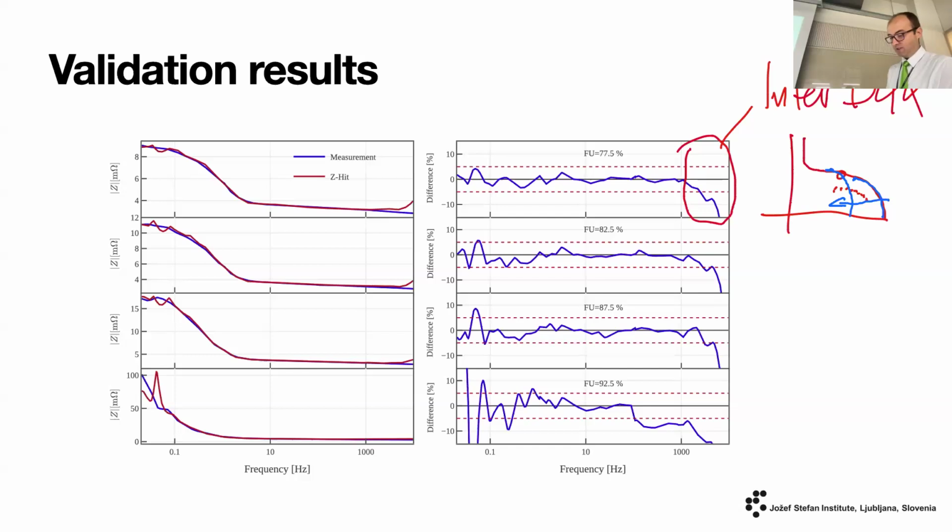And how did we detect it? We detected it because suddenly, even in the low frequency ranges, we start to look for places where our data points start to move out of the validation period. This is nothing special, the instruments are doing it for you, but this is how you can detect that your EIS measurements are becoming faulty.